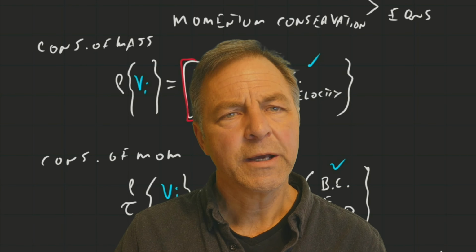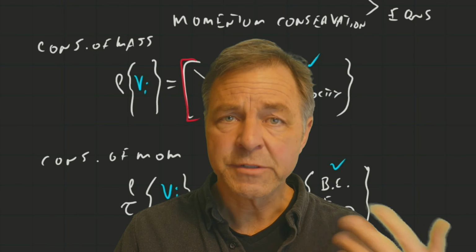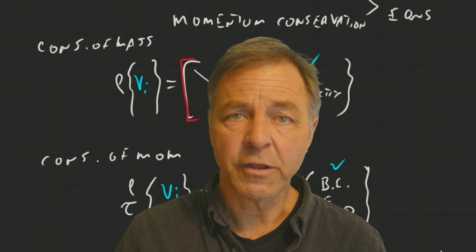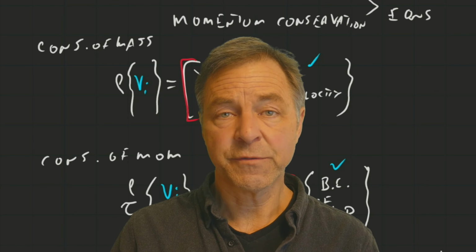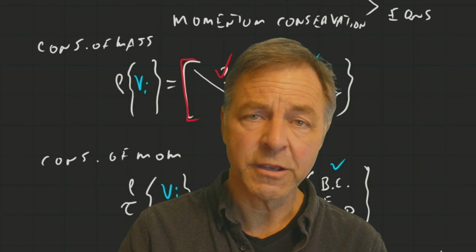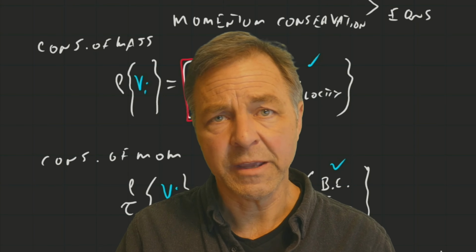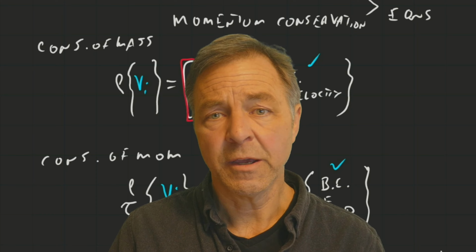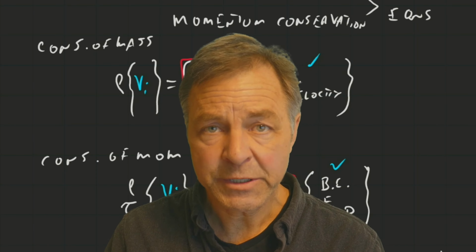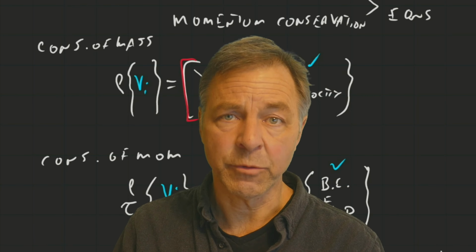And so every time you do this, as you saw, the solution has to go through iterations because, as I explained in the previous video, it's solving the finite volume method, and there isn't a closed form single matrix inversion that gives you all the algebraic equations that you can then solve. The solution has to help formulate the algebraic equations to make everything add up. So it's great to make pretty colored pictures, but don't trust them until you have proved that they're working right.